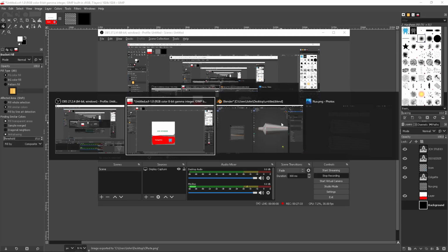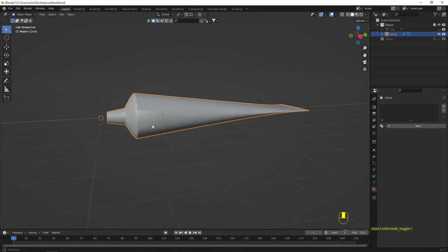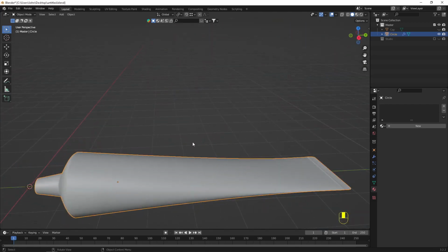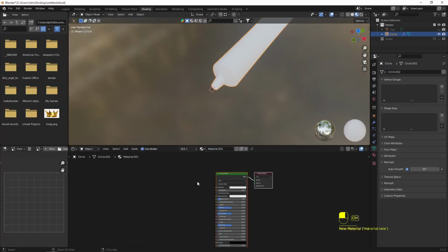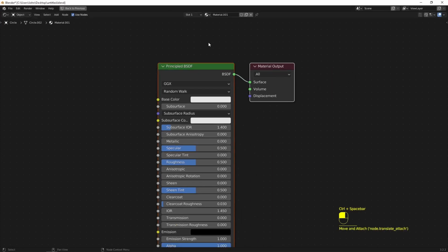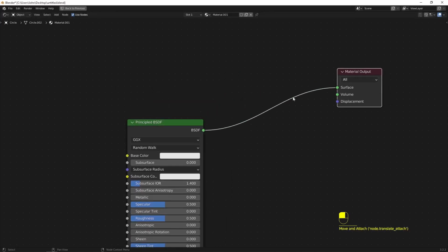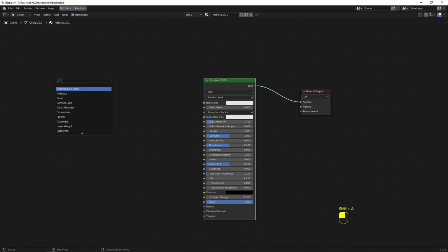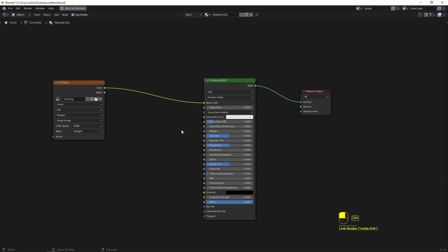Now I am going to the application, go to the layout. Now here I am going to apply two different types of things. Go to shader, create a new shading material. I am going to press Ctrl+Space to make it bigger. Press Shift+A and search for the image texture, and I am going to open that one, color UV. I am going to connect it to this base color.